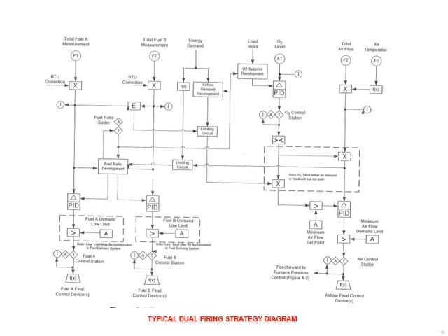Airflow is to be cross-limited by the total fuel flow inputted into the furnace. When firing dual fuels simultaneously, the airflow demand is to be characterized based on the ratio of fuels being fired to establish the correct fuel to air ratio. When firing dual fuels simultaneously, the oxygen set point is computed based on the ratio of both fuels.